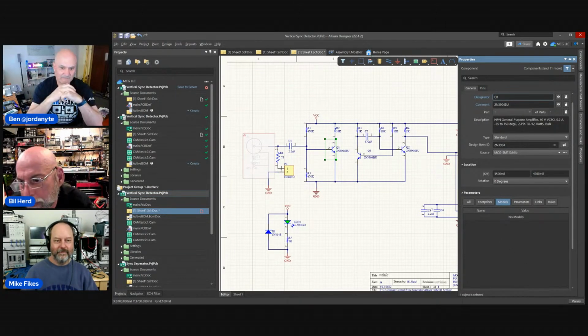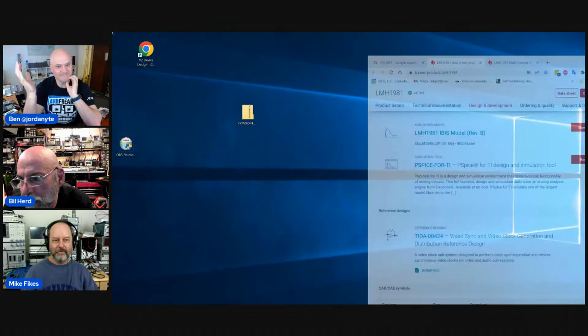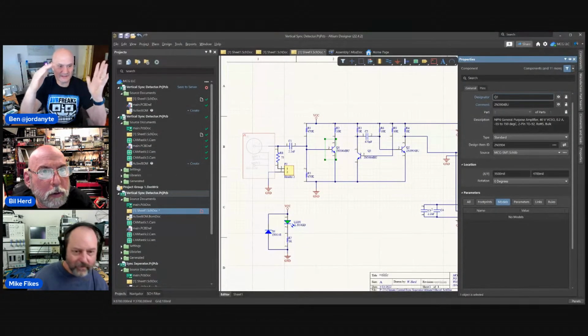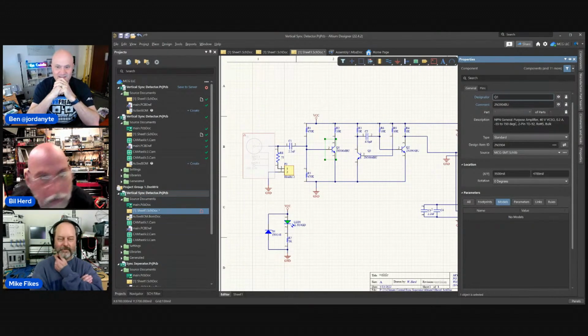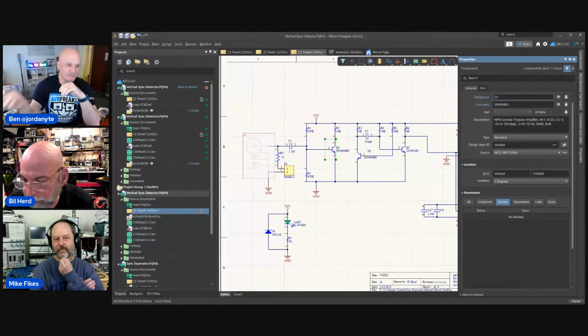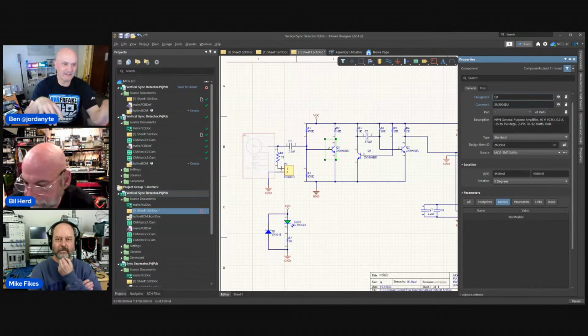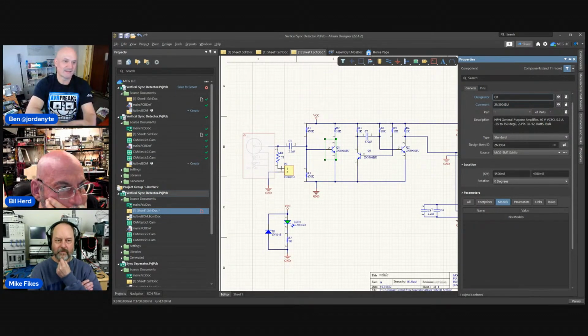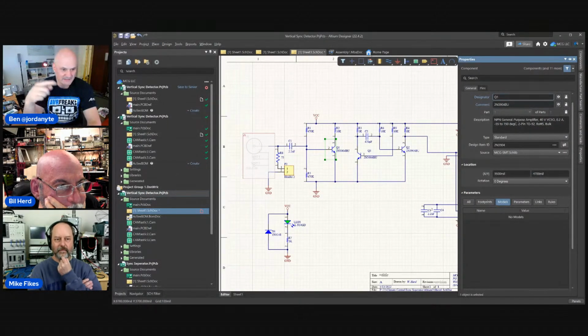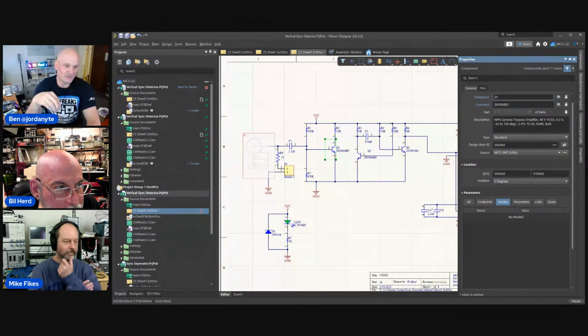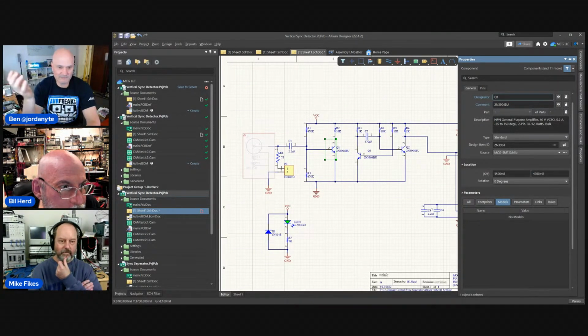So if you could see what was in it through looking at the SPICE net list, you'd be able to copy them. And they partnered up with Cadence and said, you give us a public key and we'll encrypt everything, or however it works. And so the only way to be able to open those models and run simulations with them is if you build an encrypted simulator engine and partner with them for them to give you the key. I guess the EDA company would get the public key from TI, right?